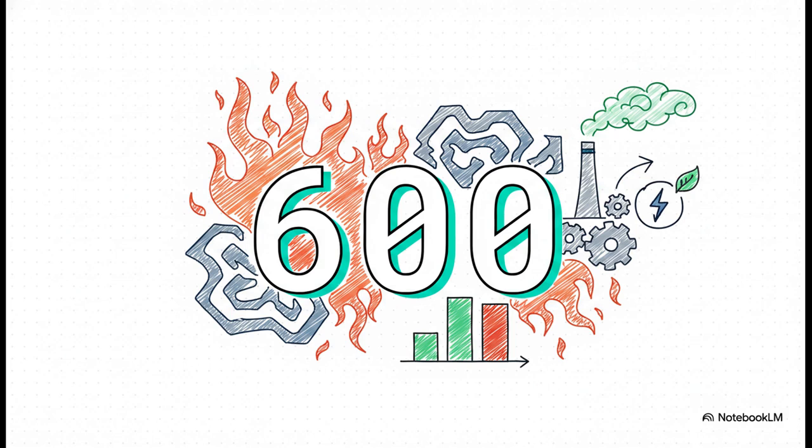Now, operating at these extreme thresholds, yeah, it strictly requires those advanced materials we discussed, which definitely drives up your initial main plant cost. But what it unlocks is just unprecedented efficiency. It aggressively drives down fuel consumption and emissions, getting you right in line with those COP21 targets. When we run the numbers through our cost of generation calculator, the ultra supercritical parameters win out every single time. They literally yield the absolute lowest long-term generation cost.